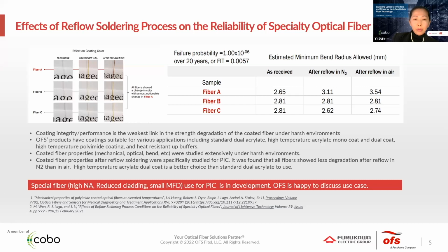And in the follow-up study in 2021, there was a further extensive study of coated fiber under mechanical bend conditions and in an emulated environment, particularly for the reflow soldering process. And the finding there is the fibers discolored, but with less degradation in nitrogen than in air.